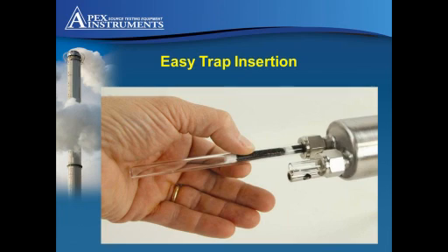The sample traps are inserted into the sampling probe; it's easy and shown here. The weekly 7-day trap change should take about 20 minutes. However, we recommend that the profile runtime is set to longer than 7 days, perhaps 10 days, just in case you cannot get to the sample location to change the traps. For example, if the elevator breaks down, or personnel sickness, or some other reason.